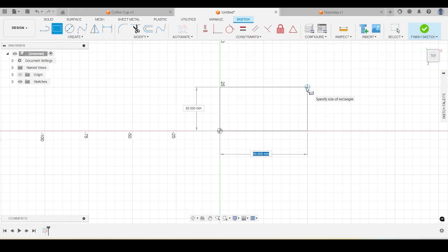But if I'm not going to make a 5 millimeter increment shape, it can be a little bit fiddlier as we're dragging across to get an accurate grab on a number. So what we can do is, if you can see it, you'll notice that the bottom dimension right now is highlighted blue. And that means that if I type in on my number pad, I can edit my dimension. So I've just typed in 51 now, and now it locks that dimension. So it's no longer coming across when I drag.